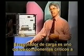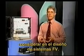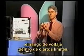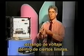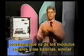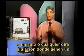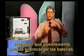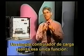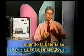In photovoltaic system design, one of the critical components that we need to be concerned with is charge regulators. We're not dealing with voltage regulators that somehow keep our voltage range within a certain set of limits. We're talking about a device that controls the amount and the flow of current from the solar modules into our batteries. Similar to a car or any other situation where you've got a charger that possibly could overcharge your batteries. A simple charge controller does that one function, controls the charge flow and either reduces it or stops the flow altogether when the battery gets too full.